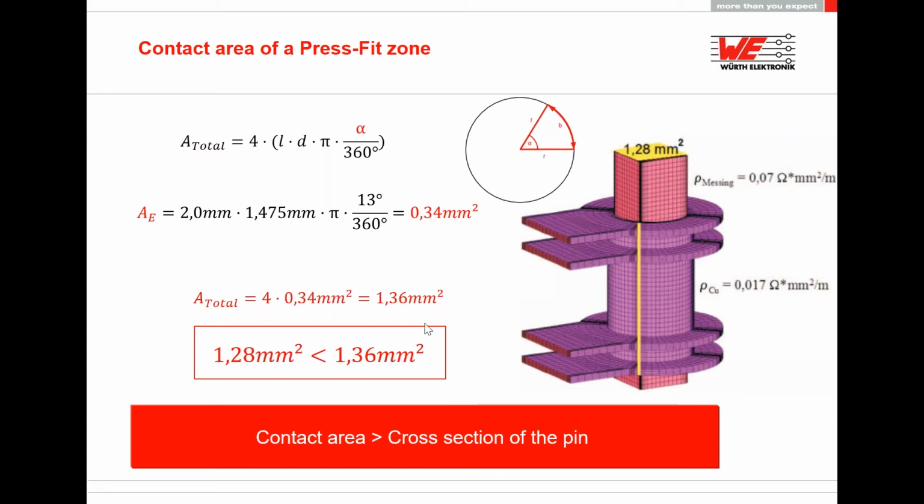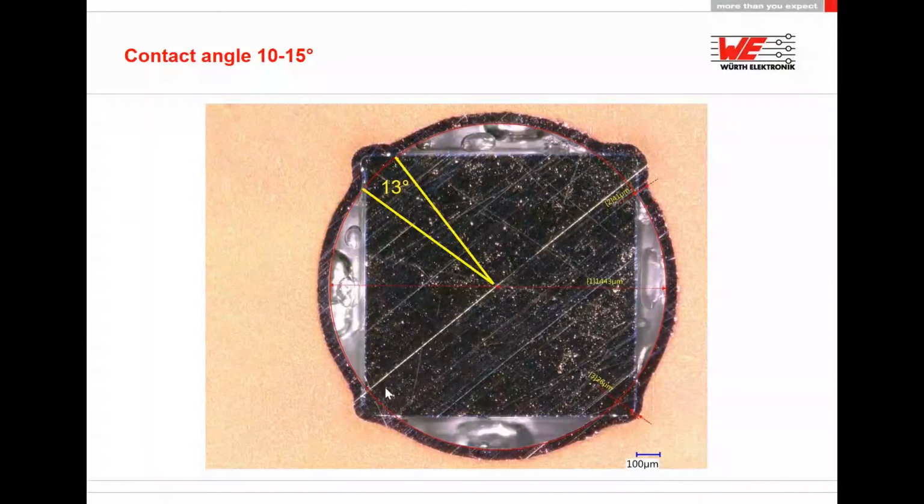So how to deal with that, and where are the limits? Yes, firstly we have to say that if the PCB thickness is a little bit lower, then the result will also be a bit lower. But we compare this connecting area. If I go one step back to the cross section, this connecting area is to the copper, and we compare this area of the pin itself, the pins are made of brass, to the connecting area of copper.